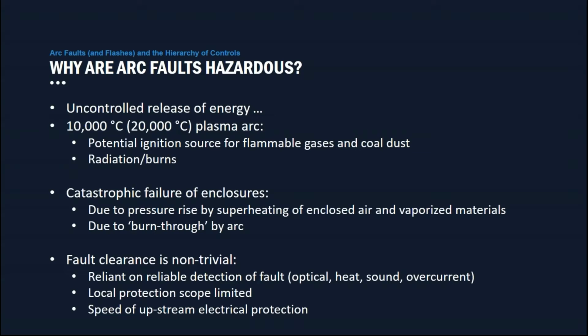One of the other hazards that also comes around is the catastrophic failure of the enclosure itself. Because we have such high temperatures, the air inside the enclosure will expand rapidly. That increases the pressure in a finite volume. And of course, it's very rare for an enclosure to be designed to withstand that pressure rise. And so you get a catastrophic fail. Another means of failure is also burn through by an arc, where a sustained arc can actually just burn through the wall of the enclosure.